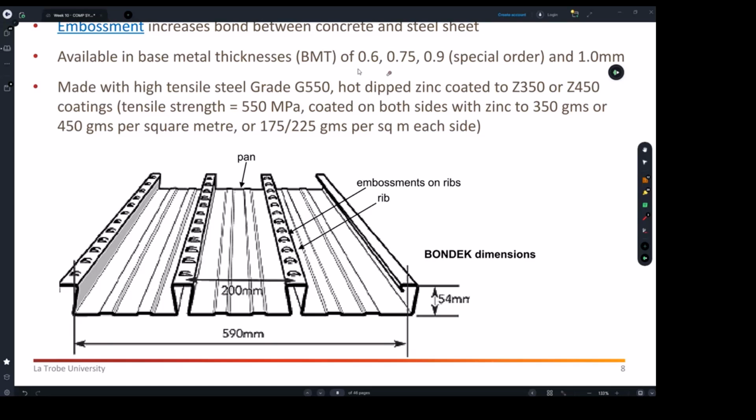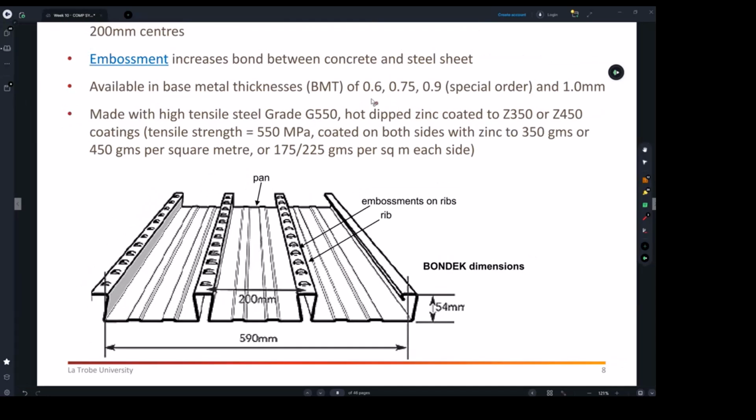The problem is during the wet concrete. We have to carry the wet concrete when still the strength is not there. And as soon as the concrete gets hard, you can take the props away. So we're going to have a look at span tables and see how to choose things.